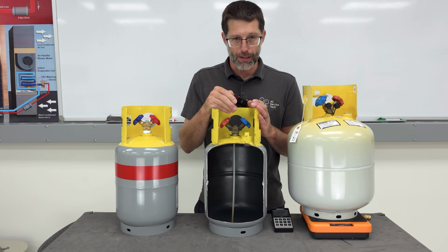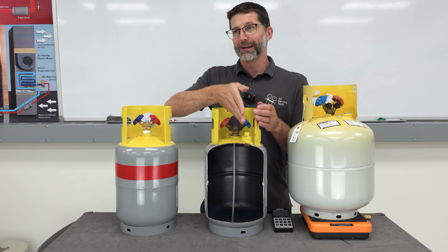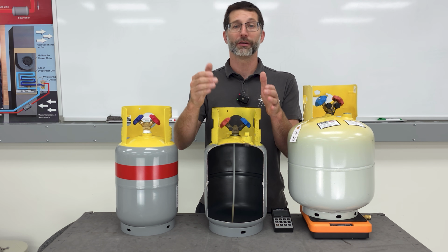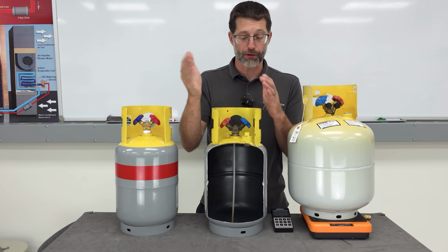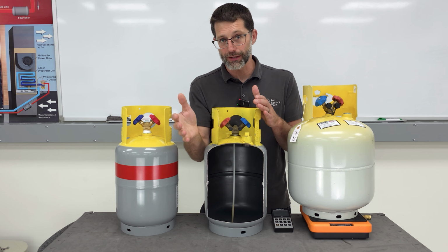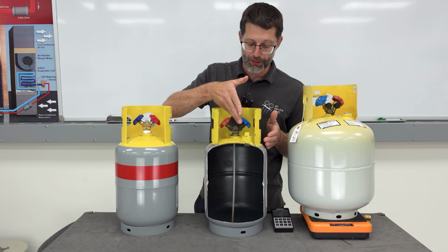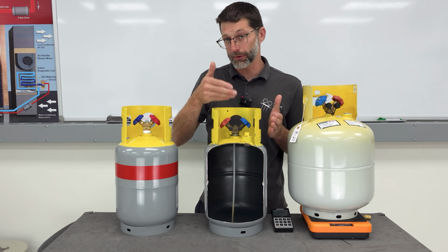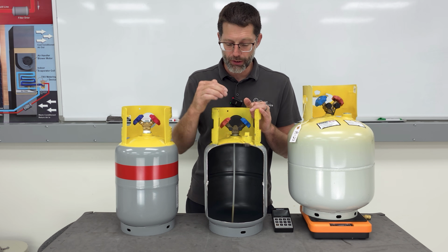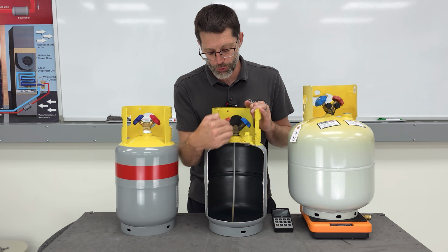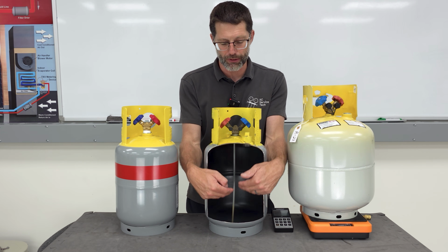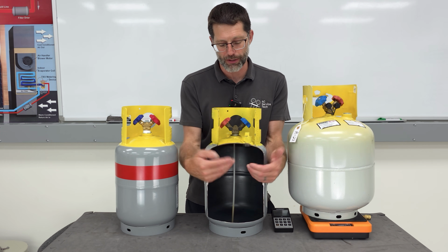But halfway through you're going to be recovering saturated refrigerant out of that system, and then towards the end, when the pressures get lower on the system, you're recovering vapor. And so even if you have a good condenser in your recovery machine, you're still putting it into the tank as a vapor, so vapor saturated refrigerant. So you could recover it into the dip tube and come down here, and then you're going to be bubbling any vapor up through the liquid into the vapor section.